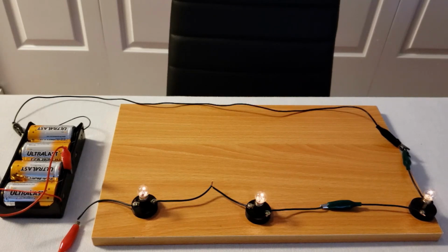So the voltage across each light bulb would be approximately 1 volt because you have 3 volts connected across all 3 light bulbs. Because the voltage across each light bulb is less, there's going to be less current flowing through it. The total resistance of the circuit is 3 times as high as when we first started. And so that's the main reason why we see this decrease in brightness: there's less current flowing in the circuit.